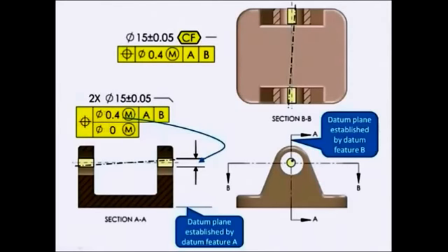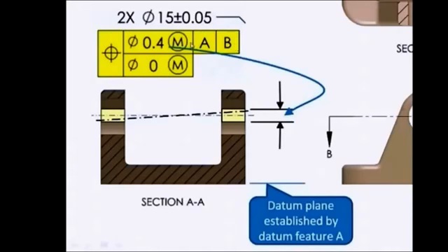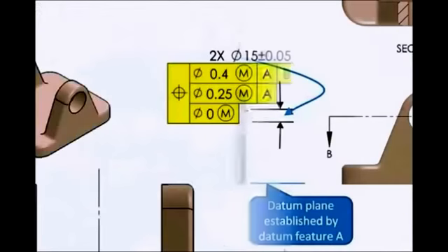So once again, composite tolerancing, one symbol but multiple tolerances. And the rule is that that upper segment is locating the features on the part. Any subsequent segments' main purpose is to tie the features together in the pattern, to hitch them together, if you will.